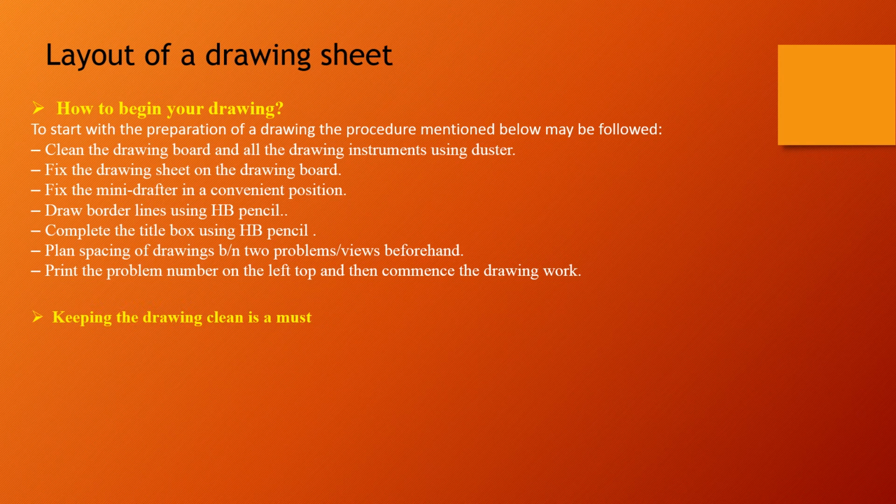Okay, now keeping the drawing clean is a must. Please never sharpen a pencil over the drawing. Number 1: clean the pencil point with a soft cloth after sharpening.